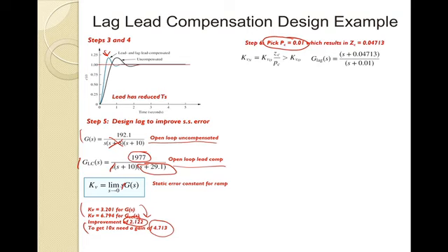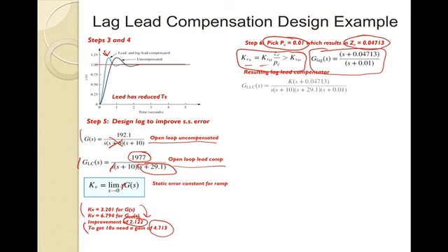And when I walk through this, what I'm going to do, based on our new versus old definition with our compensator pole in 0, this is from a previous module when we looked at the static error constants. I'll refer you back to those. But we can come up with our lag compensator. So again, when we pick the pole here, that results in a 0 there for our lag compensator. And so the resultant lag lead compensator is shown. Let's get rid of some ink.